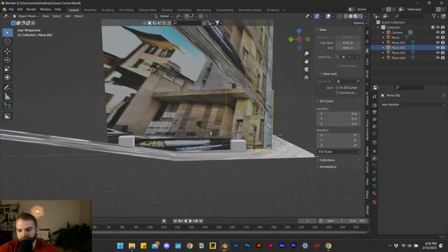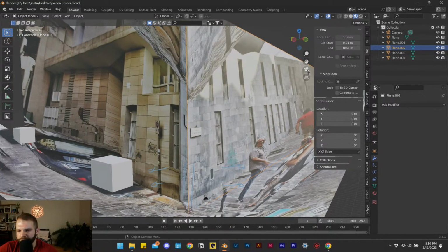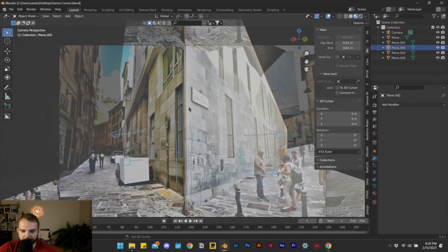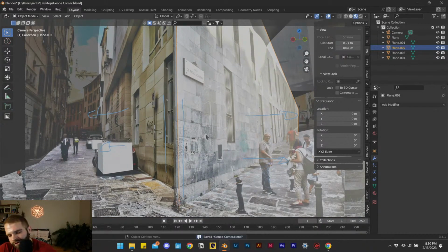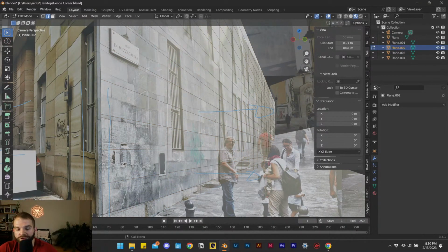Photos that are straight on can work really well in this process as well. I'll show you. Let's look at that. No, there's no straight on surface here to the camera, but we can check that out on another example. What I want to first take a look at is the fact that I can now start adding edge loops to these surfaces and start to push and pull the conditions that are on these different surfaces to actually create 3D details based off of these photos. And you can get away with doing a lot of detail with very minimal effort.